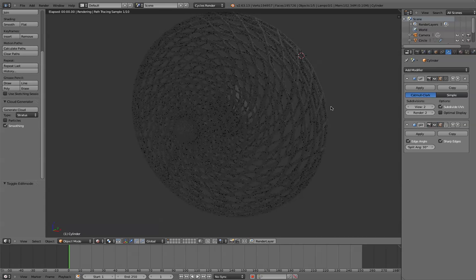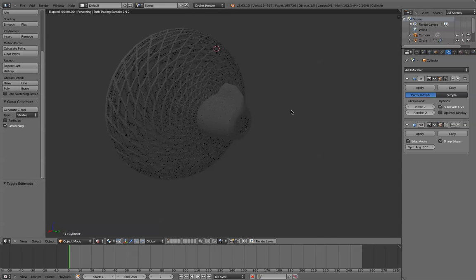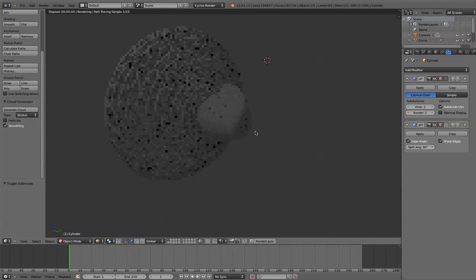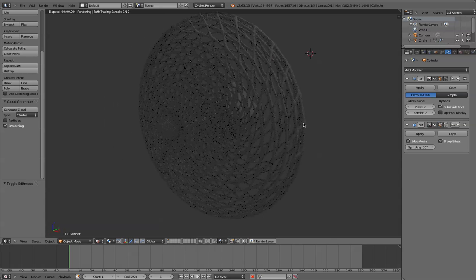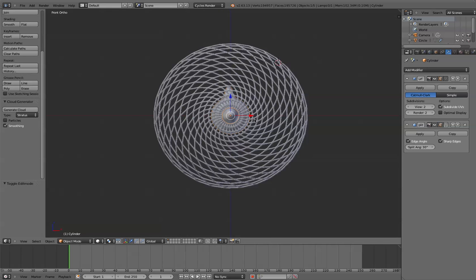This is a good thing, I think, to do when you're working every now and then, especially with the Cycles engine, is just to tick over into Rendered View and give it 2 or 3 passes on the sampling. And you can just press Z to come out of that.